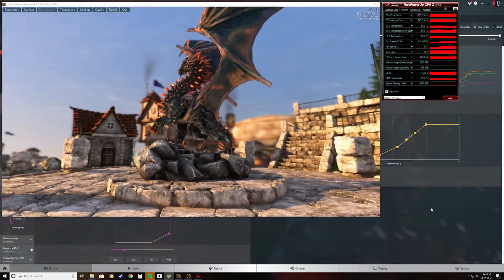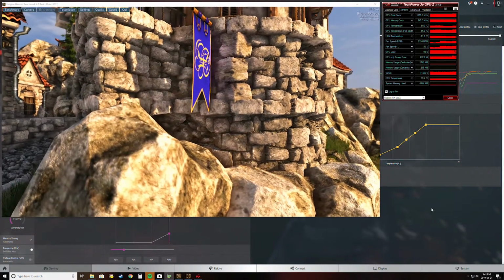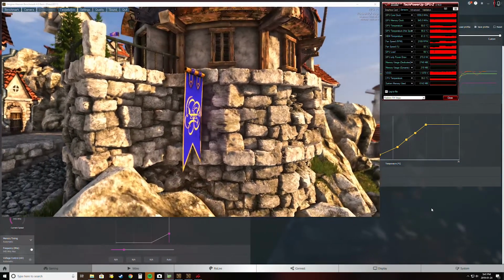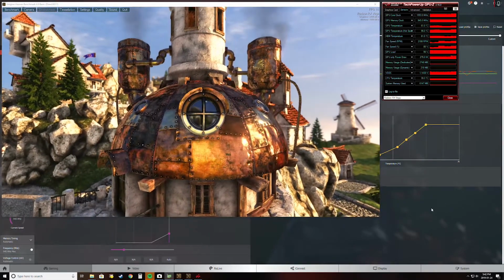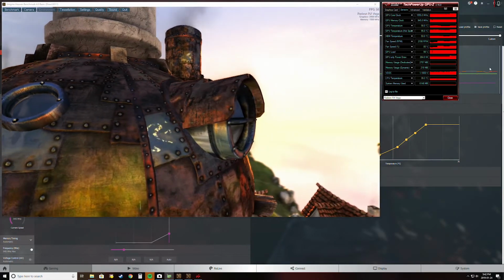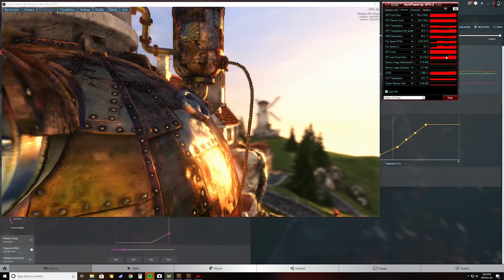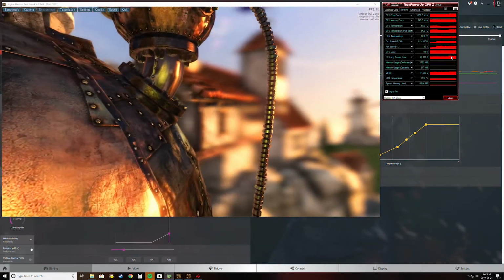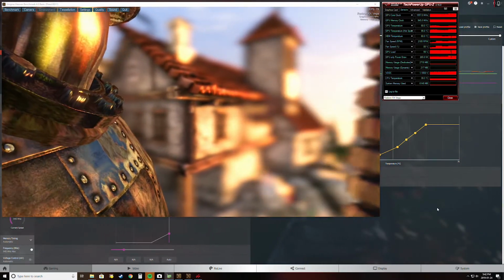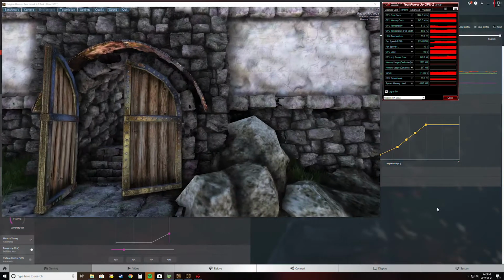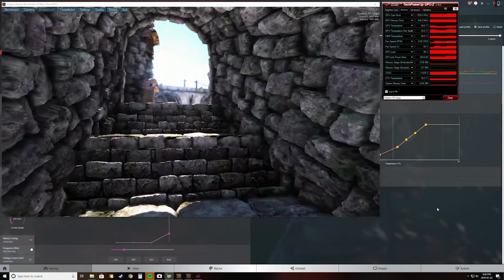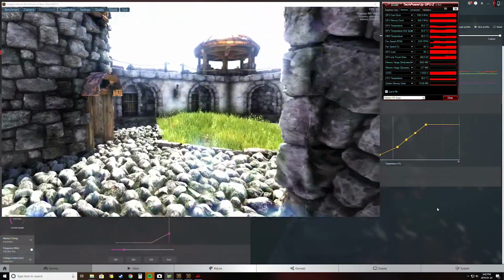So our temperatures are now back up because it's getting more voltage. And you can see that under the GPU only power draw, we're at around 275, 280 watts. And that's right over here. And that's up from 218 before we moved that slider. But we're stable at 60 Celsius, and we're putting out 1550-ish megahertz. So pretty good result already.